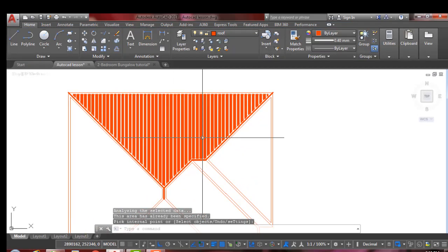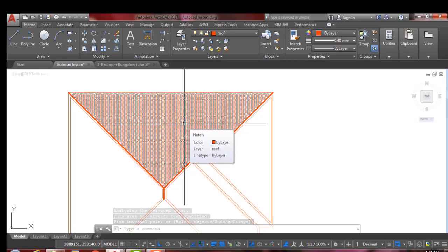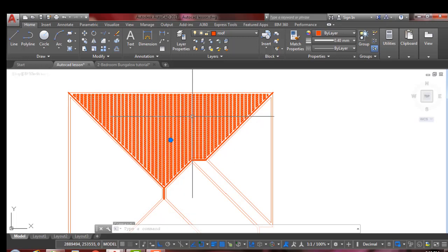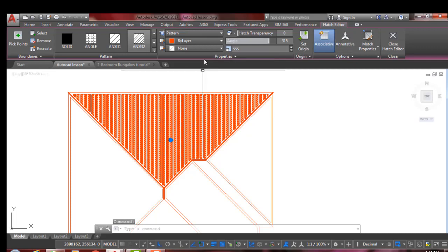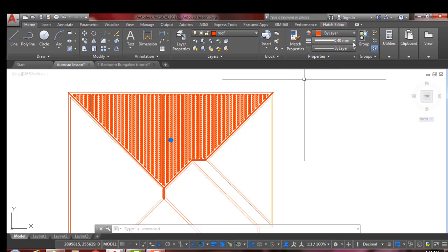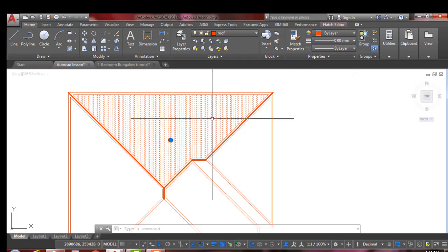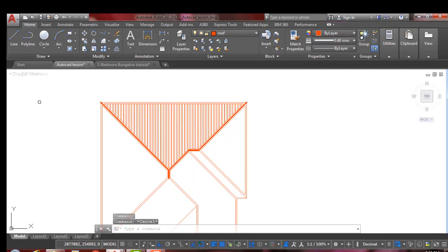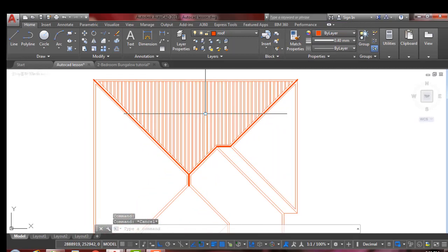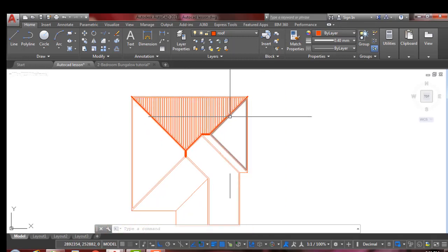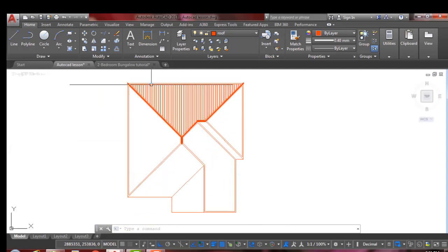But we see that the roof line is too thick, because the layer thickness that we showed is still active. So you click on it, you go back to this wall here to home. You now change it to 0.0. So you can see that it is now in the line width of 0.00 millimeters. So that's how you do the rest. You follow the same process and arch the rest for your assignment.